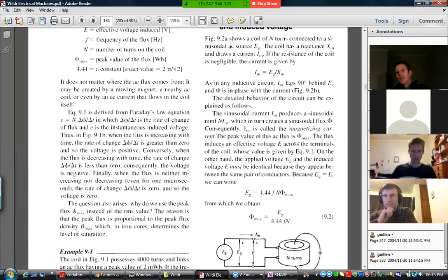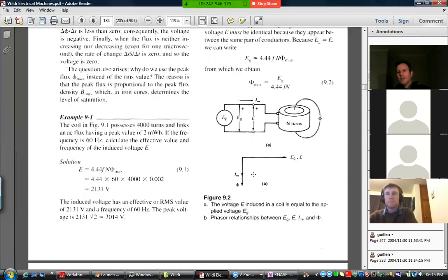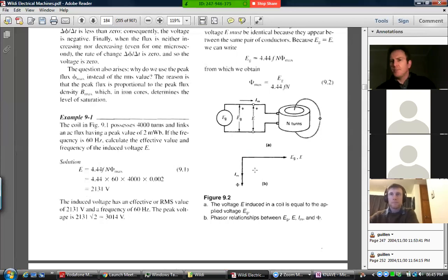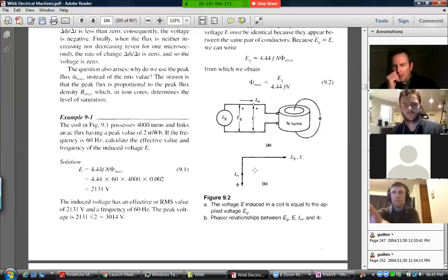All right, so we're getting a magnetizing current produced by voltage. So as a vector, in an inductor, we know we'll always have our voltage exactly 90 degrees ahead of our current. So if we choose the voltage as the phasor, then the magnetizing current will be perpendicular to that. It's 90 degrees, so it's a phase lag of 90. It's an inductor.